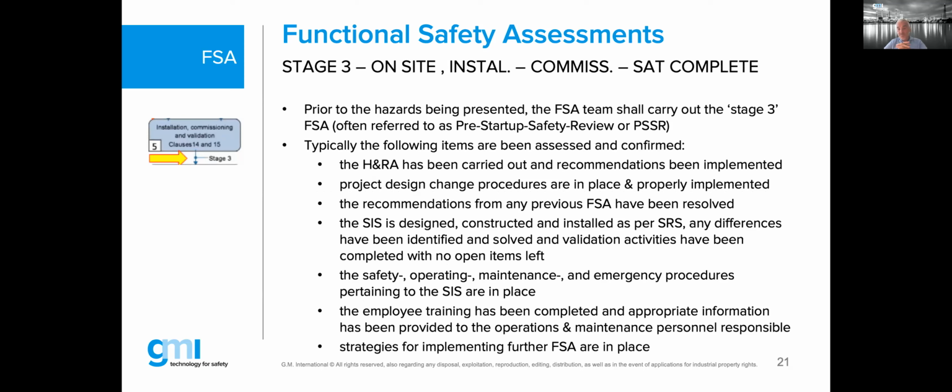And the last slide. Now we are already on site. We are with the operating company now. We are at the end user site. So on site, the installation and commissioning is now finished. Before you introduce the hazard in your installation, stage number 3 is normatively required. So prior to the hazard being present, the FSA team shall carry out stage 3.